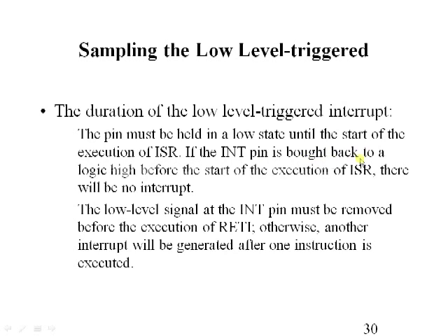If the INT pin is brought back to a logic high before the start of execution of ISR, there will be no interrupt. So we have to make logic 0 on that particular pin for a duration of 4 machine cycles. If it is logic high before 4 machine cycles or before the start of ISR, then it will not recognize the interrupt. It will not provide the service to the interrupt.